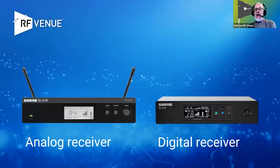So that gets demodulated back directly into audio. So we were retrieving that original audio that came out of the mic capsule. After all that, the RF link is demodulated, and we have the original audio back. Now a digital receiver puts the demodulated signal into a D to A converter, digital analog converter, or DAC. It could be converting a digital data stream, or it could be converting RF as digitally modulated, but its output is also the analog audio that came out of that mic capsule.